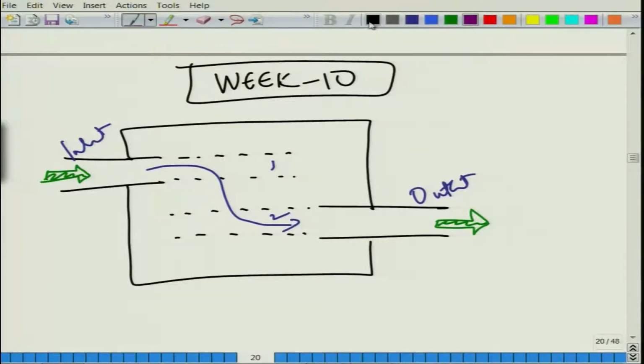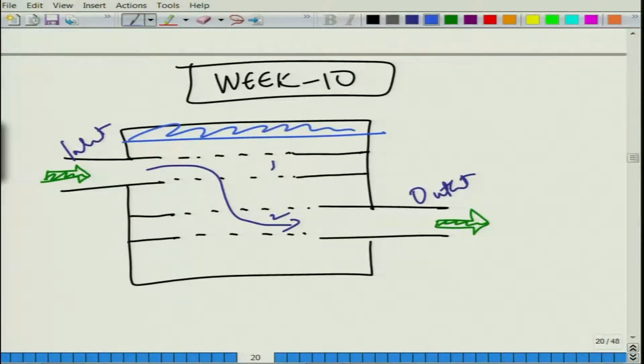Now, another thing is if you were to do it something like this. If you close it, so it becomes a closed ended cross flow element still, but it is no longer open ended, in the sense that the waves no longer discharge here, but still the waves have to go through these elements. We can keep adding more and more complexities to it. We can have a dissipative lining. So, this is just one such configuration in which the waves have to go through one path, or else you can have another configuration.